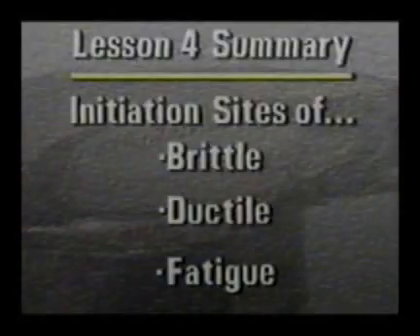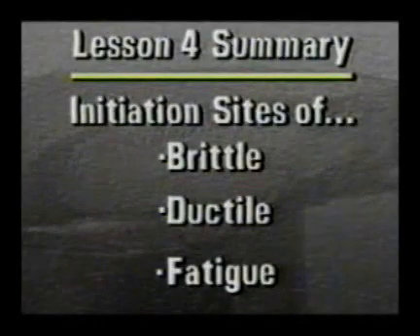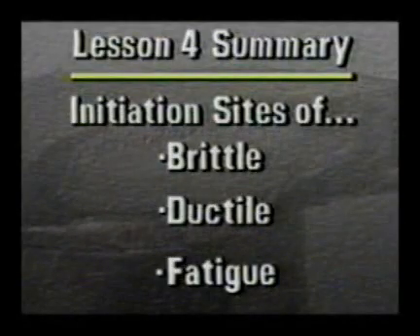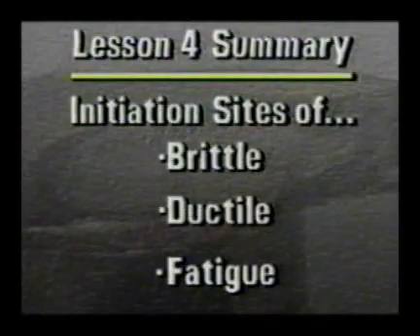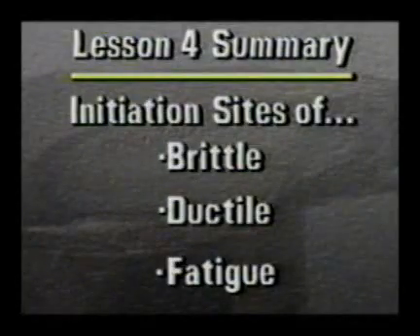In this lesson, you have learned to identify initiation sites of brittle, ductile, and fatigue fractures by using fracture surface features. We know that the initiation sites on brittle and ductile fractures are usually not as important as initiation sites on fatigue fractures, since fatigue fractures are often closely associated with the root cause of failure. This completes Lesson 4, Locating Fracture Initiation Sites.